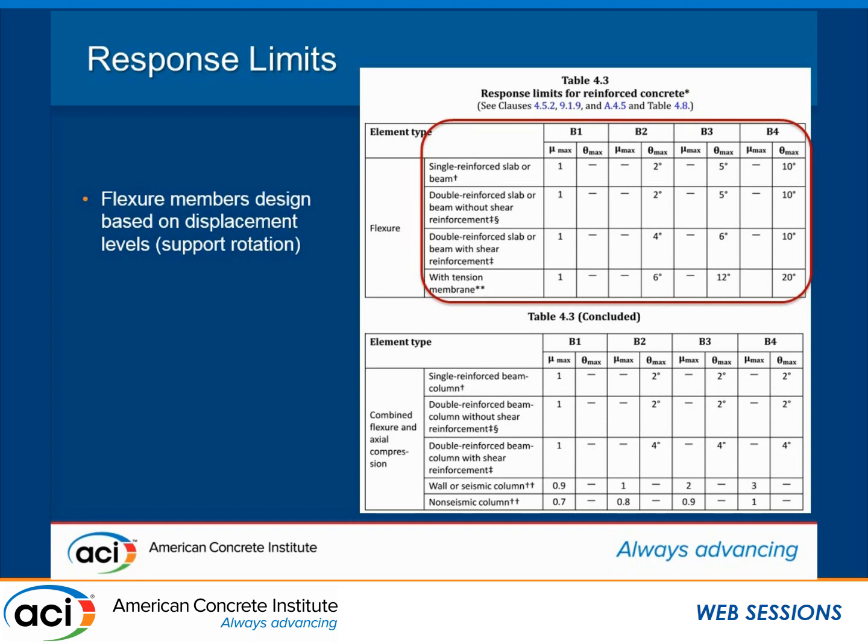So these support rotations would imply that these types of flexure members would have high measures of ductility, and to the point that it's more beneficial to look at a displacement design rather than a ductility-based design.